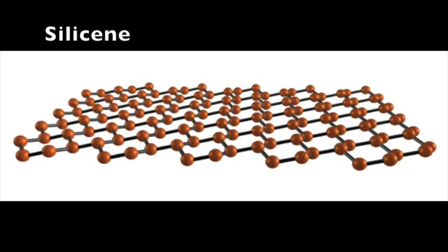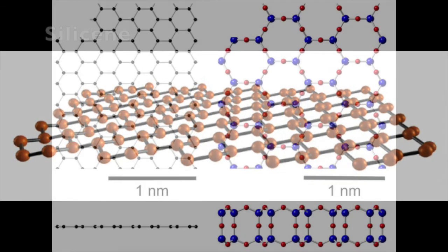Researchers observed 2D silicon structures in 2010 using scanning tunneling microscopy to study self-assembled silicene sheets deposited over silver. In 2015, researchers successfully made a field effect transistor made from silicene. The main advantage of silicene over graphene, especially in electronic applications, is that its buckled structure allows the band gap of silicene to be fine-tuned for the desired application. This is simply achieved by controlling the external electric field applied.